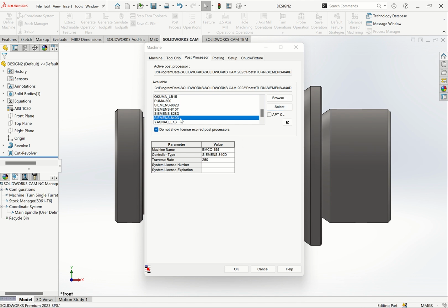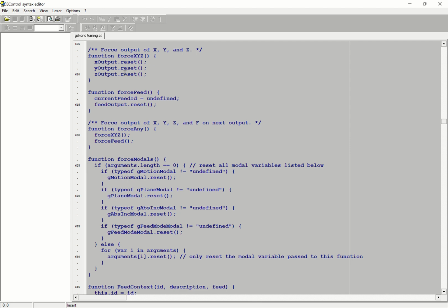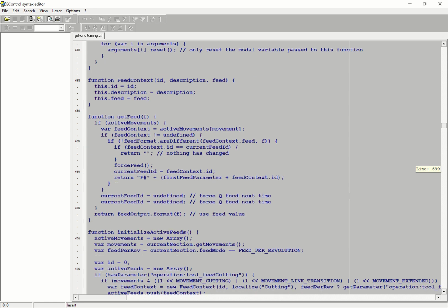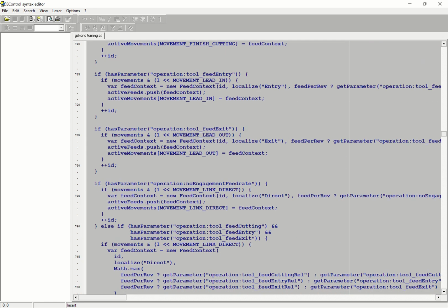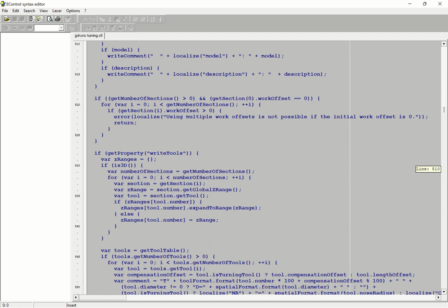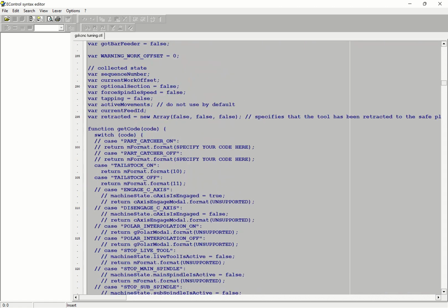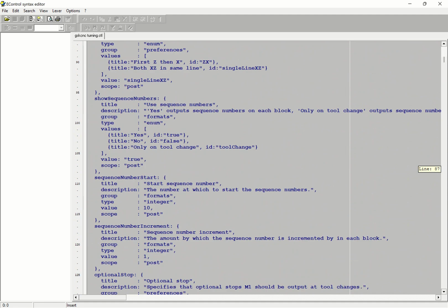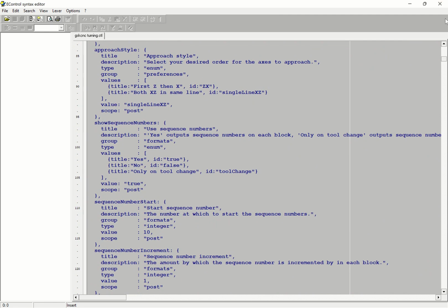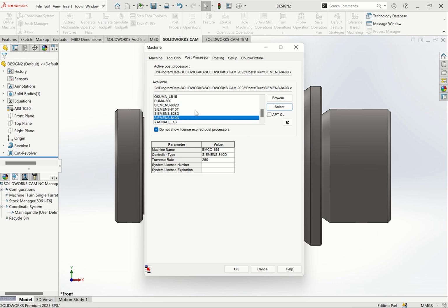Yes. So this is what you need to generate. We have installed our UPG, that is the Universal Post Processor file generator. From that generator, you're able to use the file I downloaded from Autodesk CAM for GSK. From this file, I'm able to edit my file to suit the post processor I want. But this one requires time for us to create because I cannot do it in this session. Once we do that, we're able to launch or load our file.